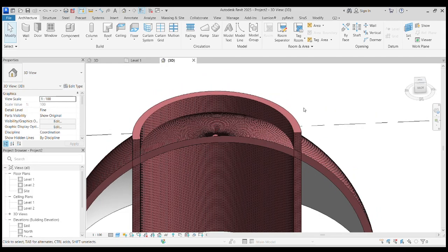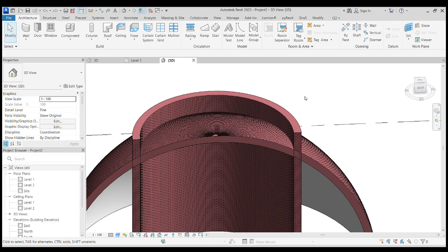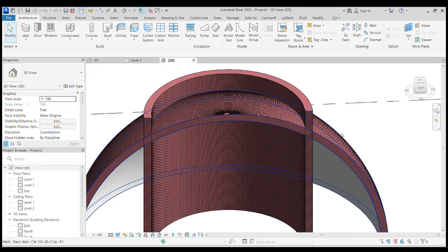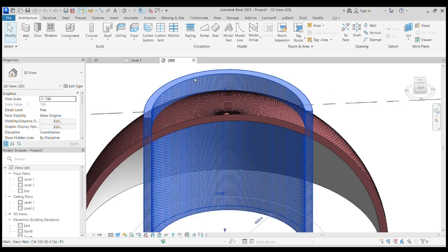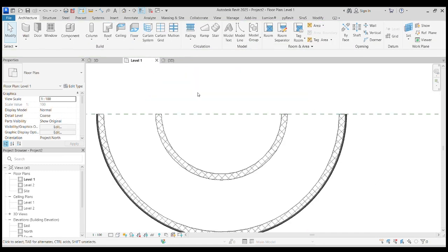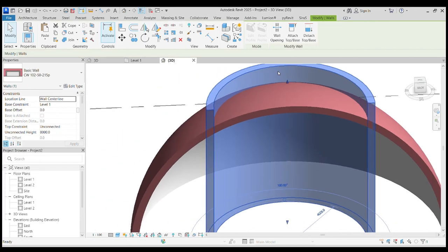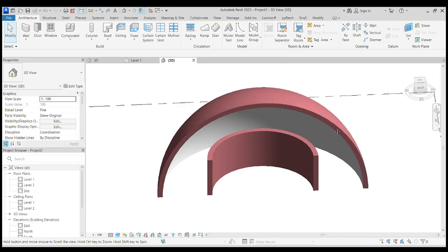Undo that. In other projects, we would just select this wall, attach the top of it to the roof, and then we would have solved the problem. However, in this case, there is no roof because these two elements both fall under the wall category. There is a small workaround for this problem that I found during my modeling of the project, which is, let's take this down,